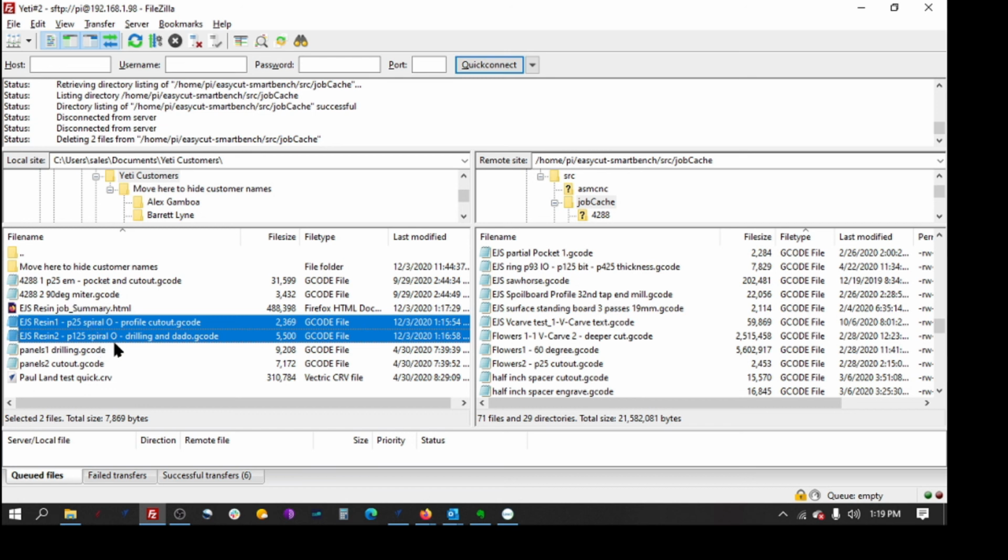If I'm going to do these in quantity, I would set up and cut multiples out first and then index them and then run just the drilling operation and not have to do a tool change on each part. I'd cut all of the table sizes out with the radiuses, all of them that I'm going to do in a given production run, say in the morning to lunch or whatever, and cut out 15 tables, and then re-index them onto a common point on the table, and then do all the drilling operations, and just put one on, drill it, run that same program again and again and again.